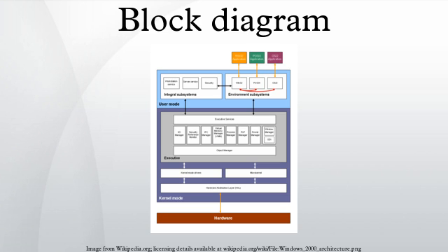Because block diagrams are a visual language for describing actions in a complex system, it is possible to formalize them into a specialized programmable logic controller programming language. An example is the function block diagram, one of 5 programming languages defined in Part 3 of the IEC 61131 standard. Since this is a real, bona fide computer programming language, it is highly formalized with strict rules for how diagrams are to be built.